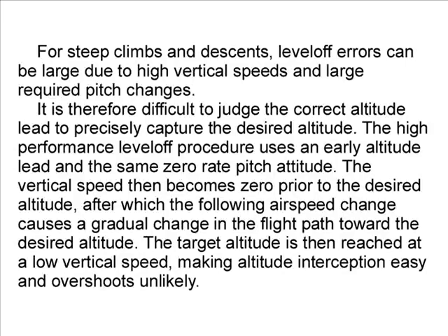For steep climbs and descents, level-off errors can be large due to high vertical speeds and large required pitch changes. It is therefore difficult to judge the correct altitude lead to precisely capture the desired altitude. The high-performance level-off procedure uses an early altitude lead and the same zero rate pitch attitude.